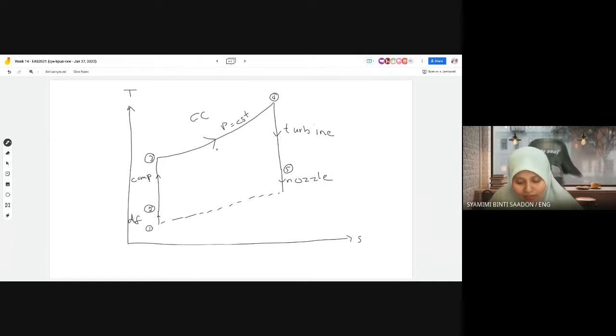So this is the basic component in an aircraft engine. Just now, the temperature and pressure of the gas at the turbine exit. The turbine exit is point number 5. So the first question, we want to find pressure and temperature at the exit of the turbine, P5 T5. But normally for thermodynamics or propulsion, even though the question asks you to calculate P5 at the turbine exit, we need to start from the first point, from when the working fluid enters the engine or the cycle. Start with point 1, point 2, point 3, point 4, and then we can get point 5. So we have to start from the beginning.